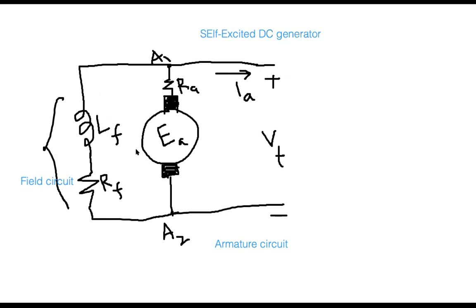So therefore, can you just guess one possible shortcoming or limitation? That if there is no voltage built up here for some reason, then the field might not be excited. And if the field does not excite, meaning that you might get zero voltage here.